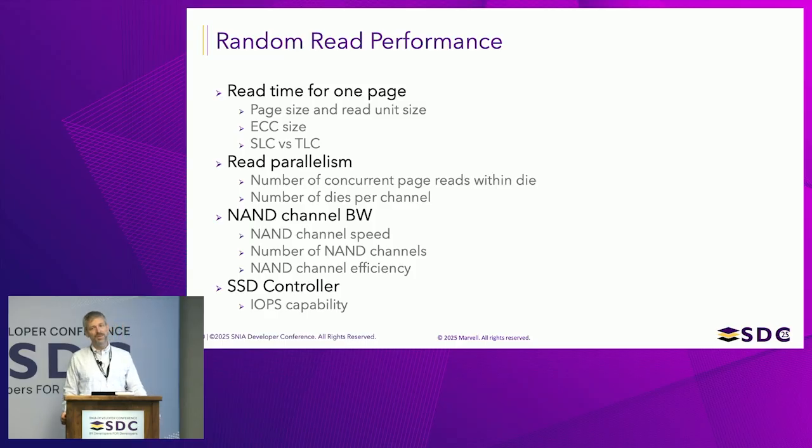And then, as I said before, one key factor in terms of improving read time is to move from TLC NAND to SLC NAND. So instead of having 8 voltage levels within a NAND cell, moving towards 2. So that also improves read time significantly.